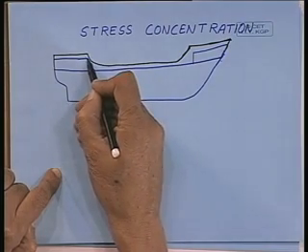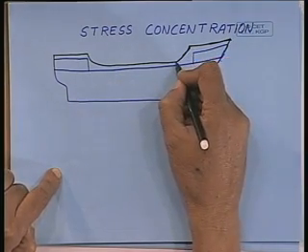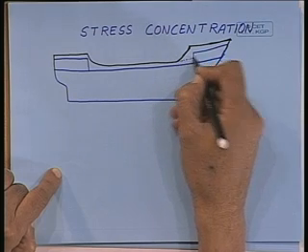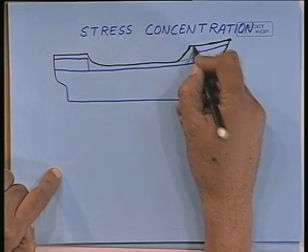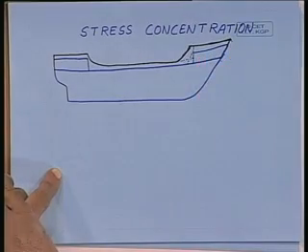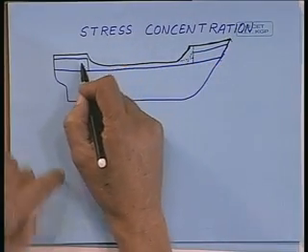So there is a discontinuity here. Now if we wanted to give the bulwark, we could have finished it here, put a ladder sort of thing here, and then start the bulwark and then finish it. But we don't do that. Now there must be some reason why we are not doing that. Can you tell me what are the reasons?